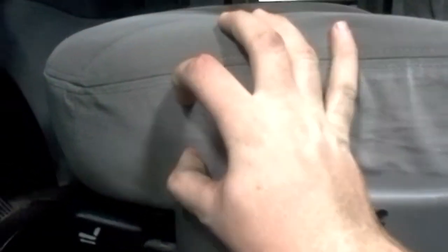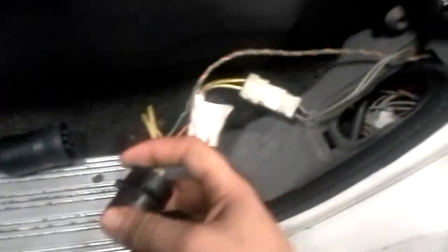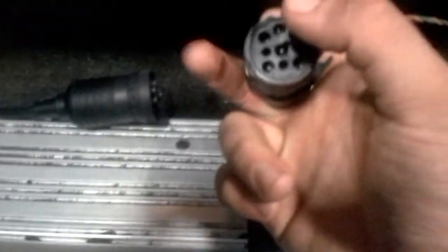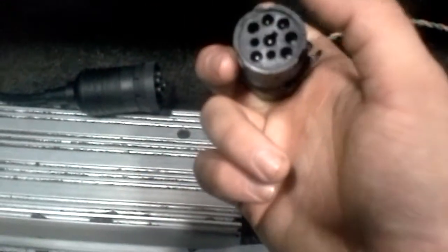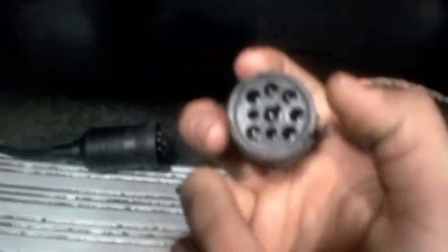On each side of that ladder, as I was saying, there's a resistor, and depending on the manufacturer specification, that determines the resistance of each resistor. Normally it is 60 ohms on each side of that ladder. Now, if you want to make sure you don't have a communication problem inside the wires going up into the truck, you can take your voltmeter, find positive and negative, positive and ground, and measure for ohms with the truck off. Okay, measure for ohms.